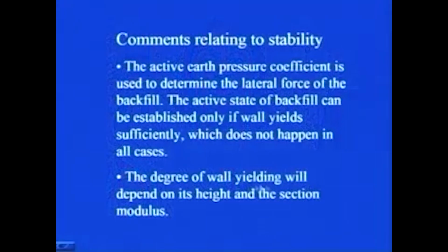Usually it is not generated in all cases. So we must take into account whether the active or passive condition is really getting generated or not. The degree of wall yielding will depend on its height and the sectional modulus.